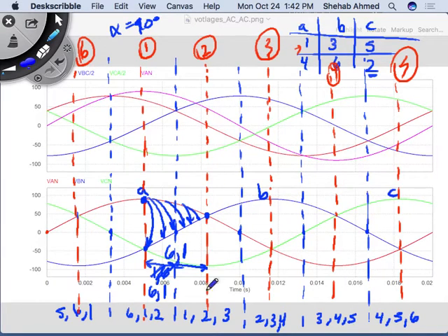I can turn on here. Here I provide the gate signal for 2. 2 is phase C, lower one, right? 2 is phase C, lower one. So current can go back from phase C, right? And which devices were on here as well? 6 and 1 were on. 6 and 1 were on here.